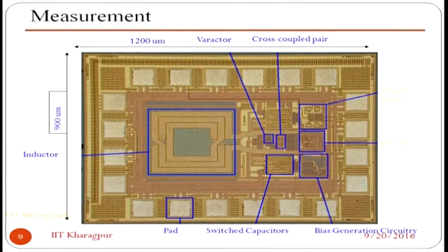Anyway, for today's class, this is the pad, and how this is connected to the external pins and so on. So you can find this is a simple LC VCO with, say, 900 megahertz oscillations. That is 1.8 gigahertz oscillations, and the divider will be there so that you can get ultimately 900 megahertz. And this is a bias generation circuit. Somebody talked about that. This is the inbuilt bias generators inside the chip.